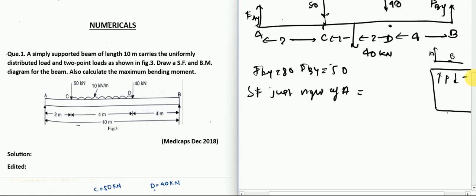And you have force at A also, and you have force at C also. So either you can calculate from C what is the shear force at B, or you can calculate from A. This will be on the left side, and this will be on the right side of B. So if you are calculating at B from the left side, from A, it will be an upward force of whatever it is, let us say FAY. So this will give you the positive at B because it is in the upward direction.